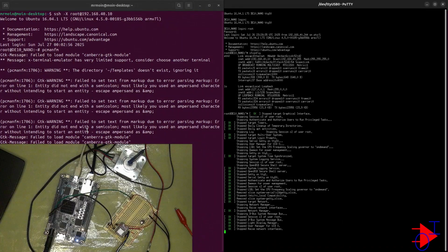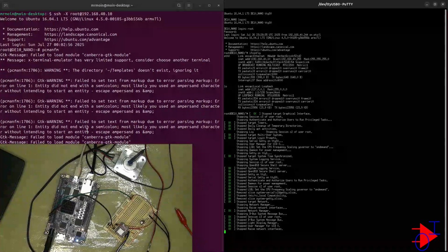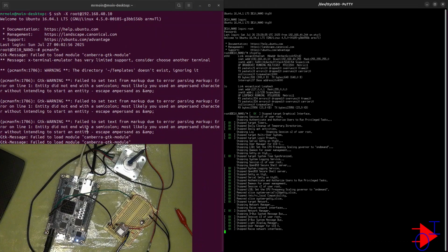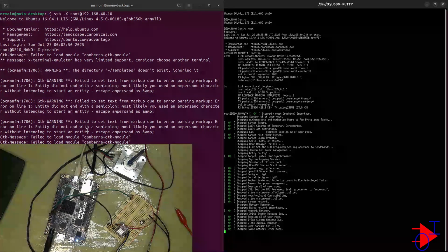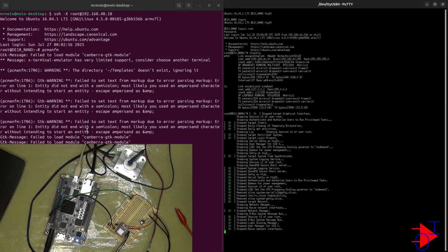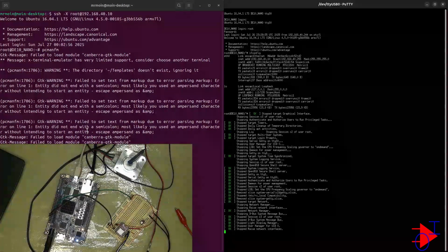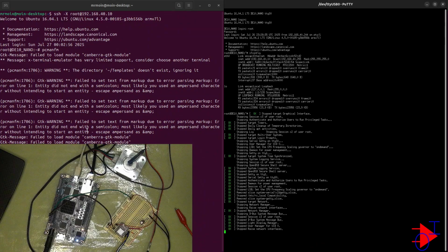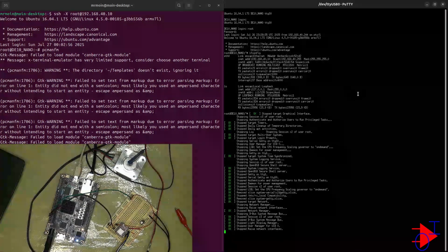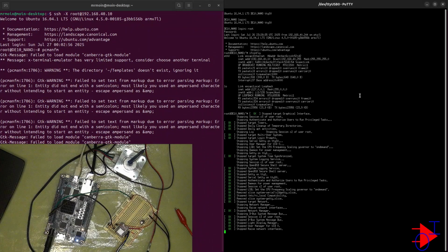So remember, we converted the SOF file into an RBF file, and then we moved that RBF file into this D10-nano SD card image, and we also changed its name to match the one that was loading by default, basically replacing that file.